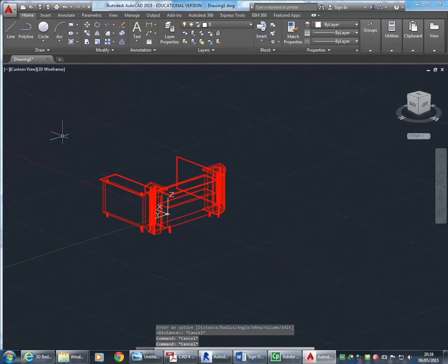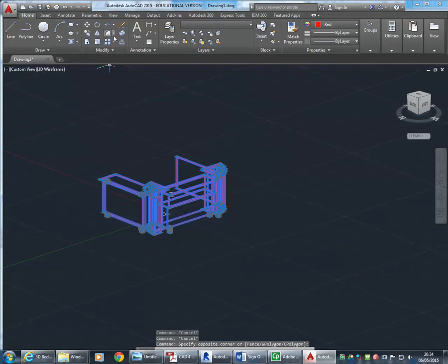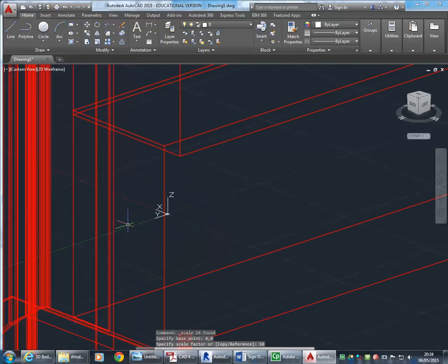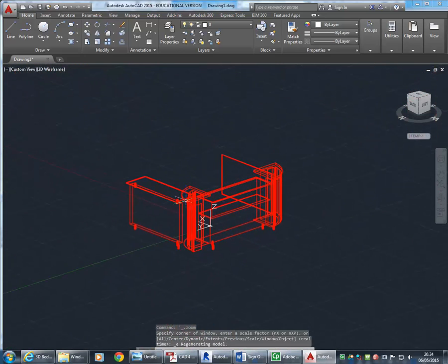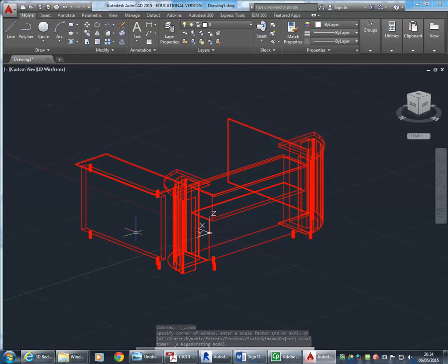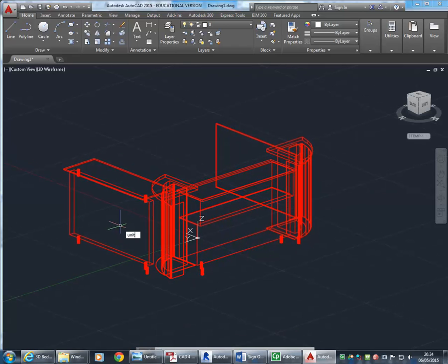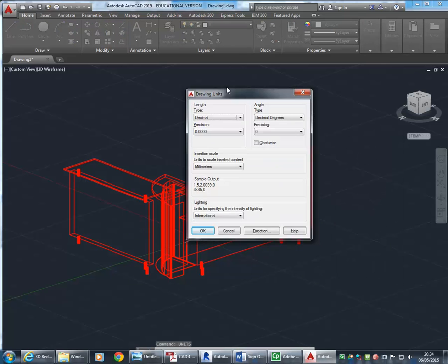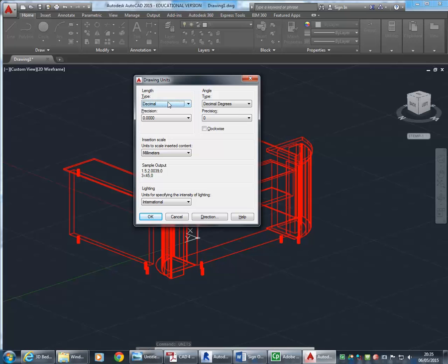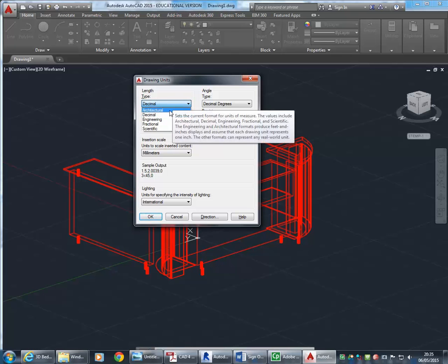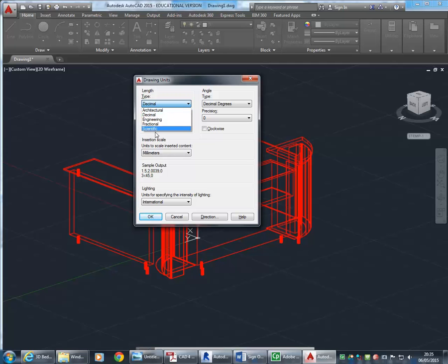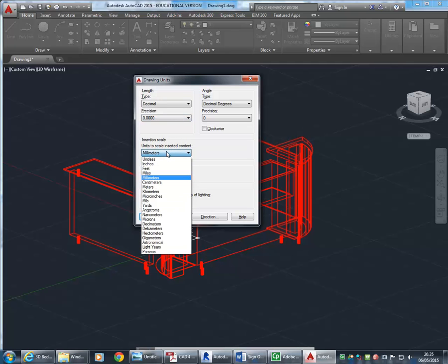So we can say, right, it's probably centimetres, which means if I scale it, just selecting it all using the scale tool, 0,0 is the base point, and then the scale factor I'll make 10, which should convert it into millimetres. And if you don't know, AutoCAD doesn't actually have a unit setting. When you type units, it brings up the units tool. Also, it does have a unit setting, but not for measurement units. This just is going to give you the number display options. But there's no option to choose metres or inches or anything like that. There's only an option to scale inserted content, which is a different thing.